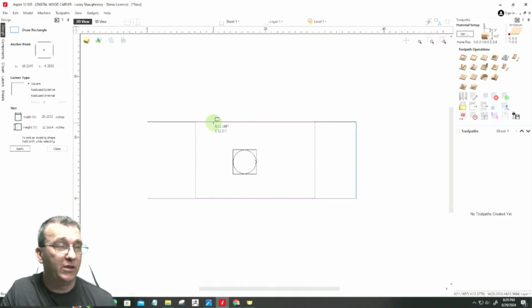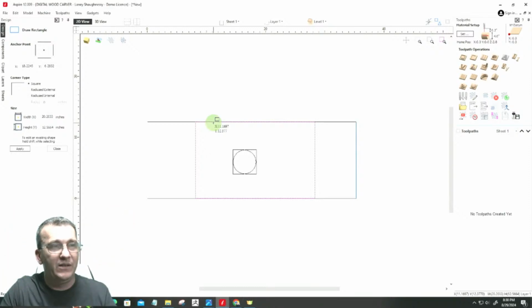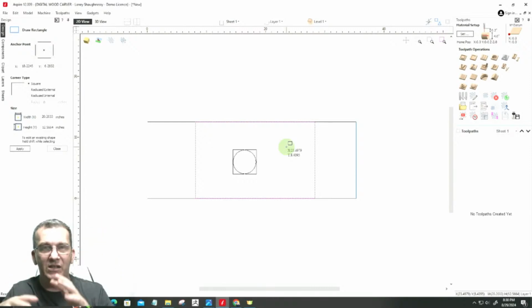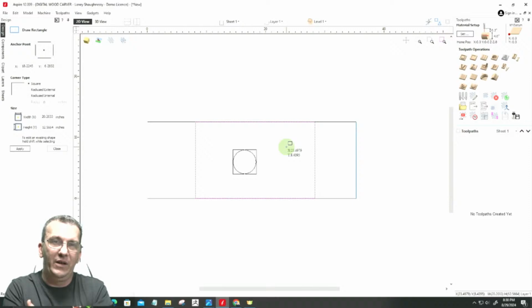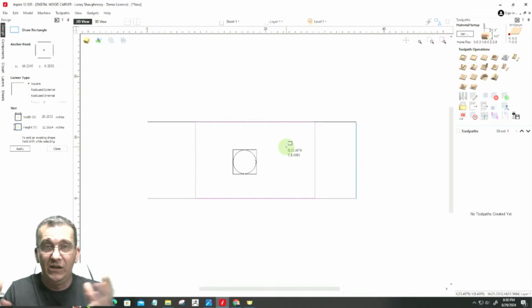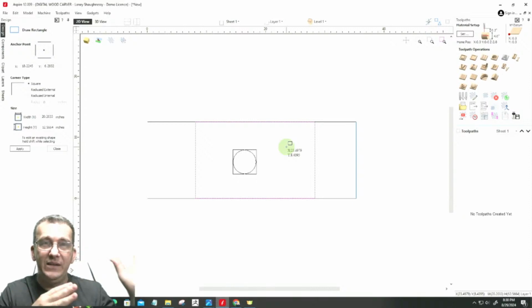That's fine. As long as you define, as long as you lay out, hey, this is where I'm carving. Don't touch this. Carve in here. That's good. That's fine. No problem. Now, in my case, my blank is starting out at 4" by 4". And when it's all said and done and squared back up and everything, we know from the drawing that my actual table leg was 3 3/4, and in this case it's going to be 3 7/8. I still have room if I wanted to go down to 3 3/4. I still got another 1/8 of an inch I can mill off, so I'm good and everything. I don't need to leave a certain area alone.